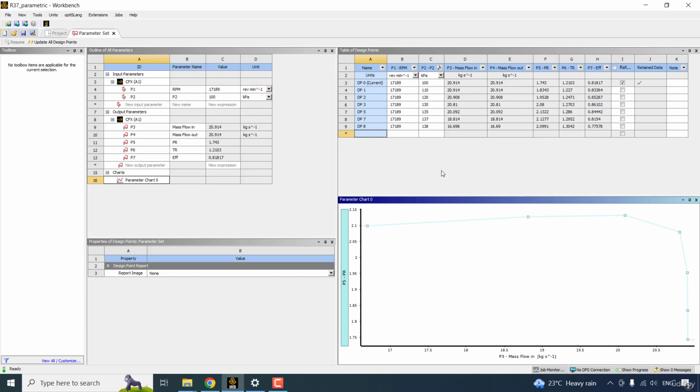We can also set the number of iterations as a parametric input in CFX preprocessor. So we can specify more iterations for the last 2 points. By this method, we can predict the compressor map more accurately. Another method is to specify a mass flow boundary condition for the points near the surge region, that is the points near the higher back pressure zones, where the pressure ratio will be almost flat but the mass flow rate will keep varying.